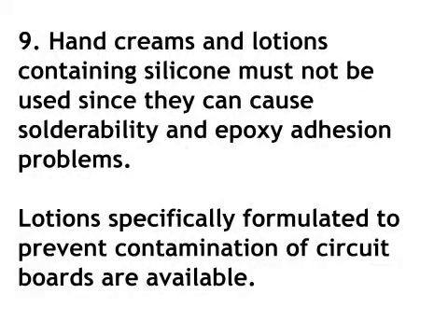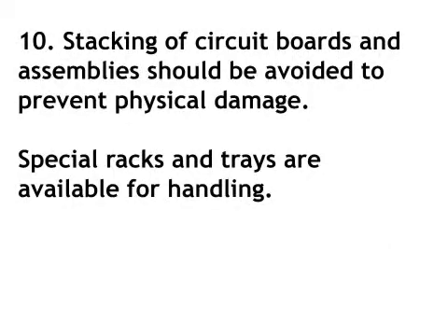9. Hand creams and lotions containing silicone must not be used since they can cause solderability and epoxy adhesion problems. Lotions specifically formulated to prevent contamination of circuit boards are available. 10. Stacking of circuit boards in assemblies should be avoided to prevent physical damage. Special racks and trays are available for handling.